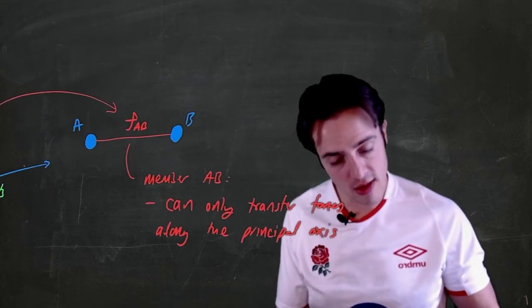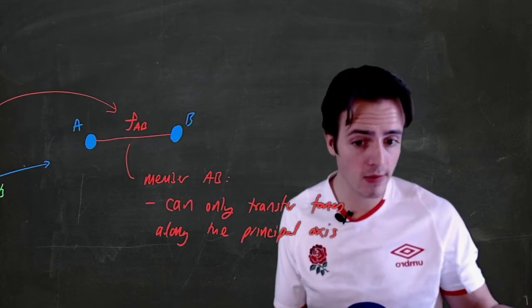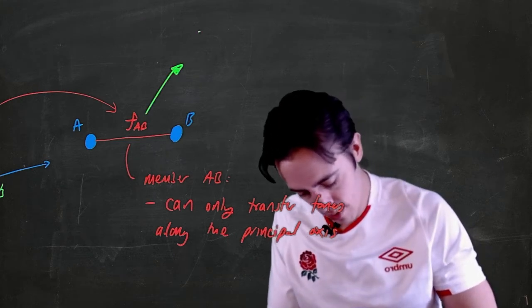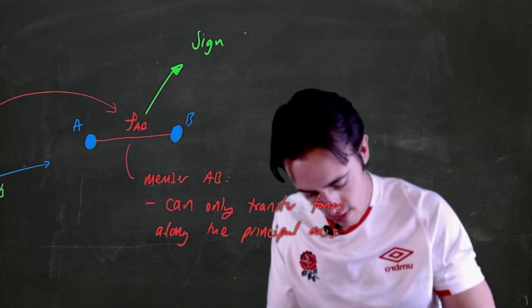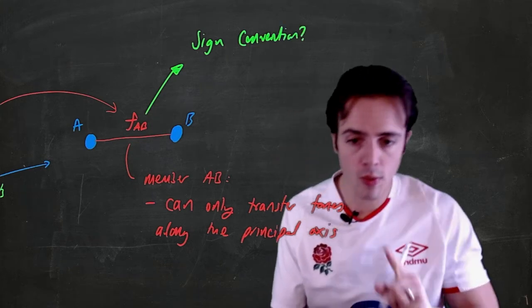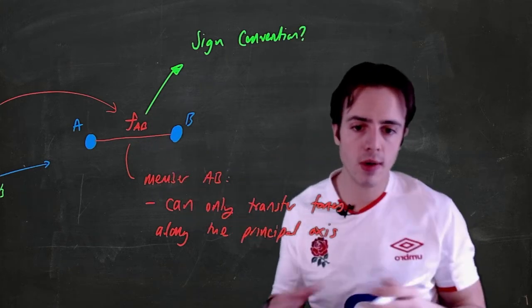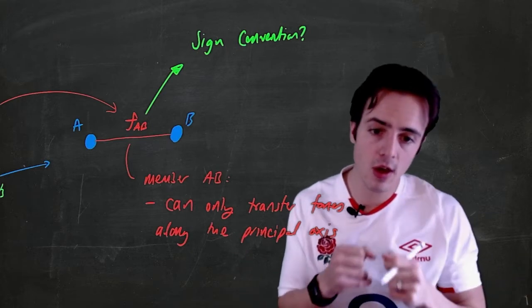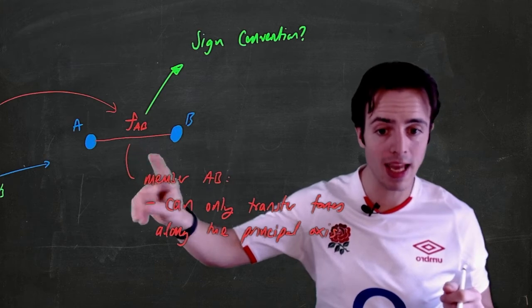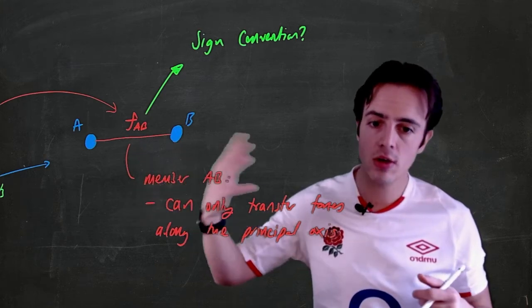Now sign conventions here, I don't particularly care what your sign convention is, as long as you are consistent. What do I mean by sign convention? Well, we know that because this is a two-force member that's capable of transmitting forces just along here, it means that this member can either be in tension or in compression.